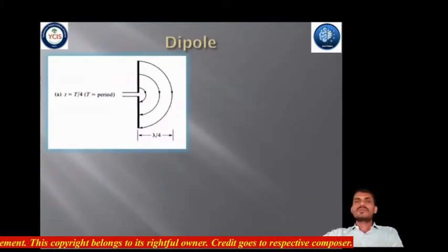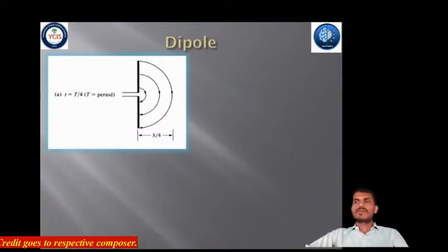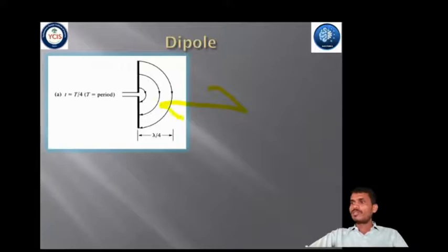Now, the third source is the dipole. Let us attempt to explain the mechanism by which the electric lines of force are detached from the antenna to form the free space wave. This will again be illustrated by an example of the small dipole antenna, where the time of travel is negligible. This is only necessary to give a better physical interpretation of the detachment of the lines of force. Although a somewhat simplified mechanism, it does allow one to visualize the creation of the free space wave.